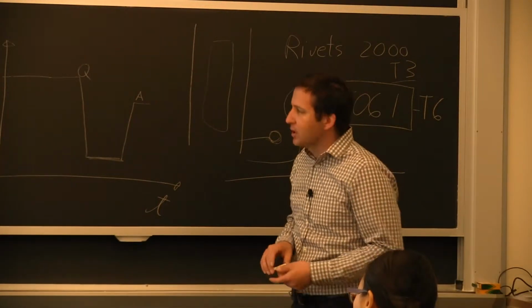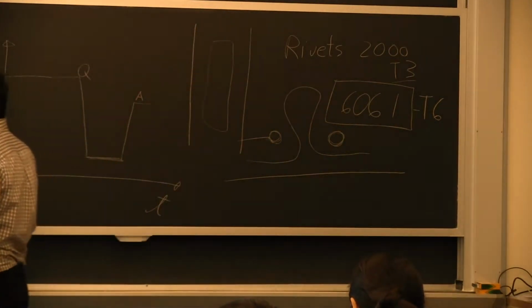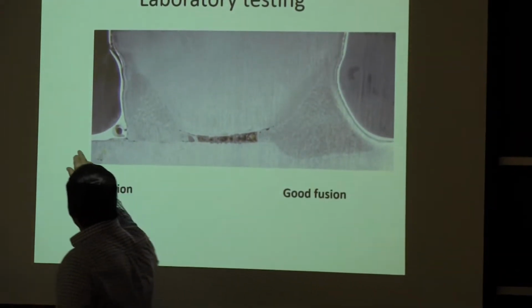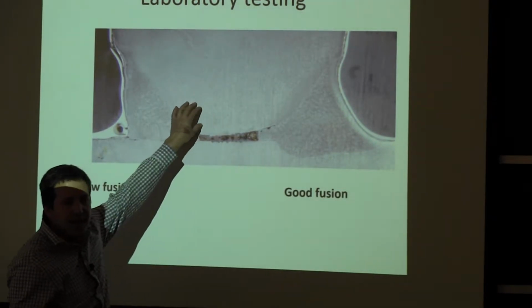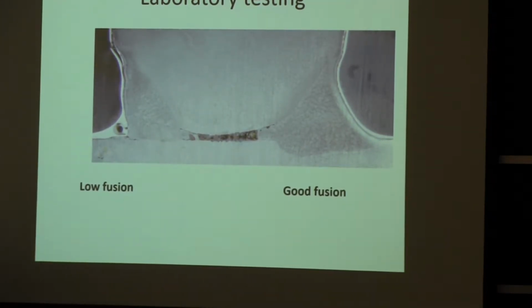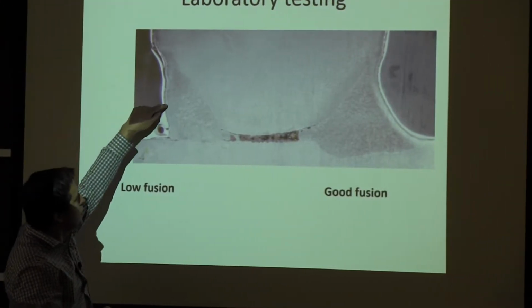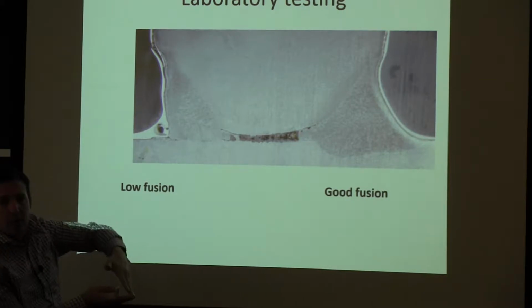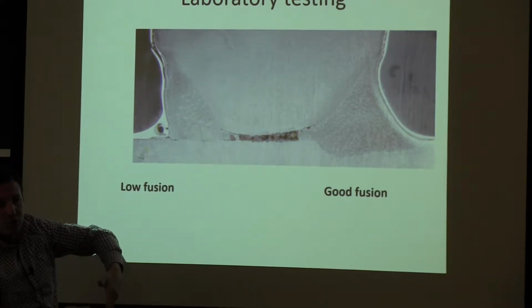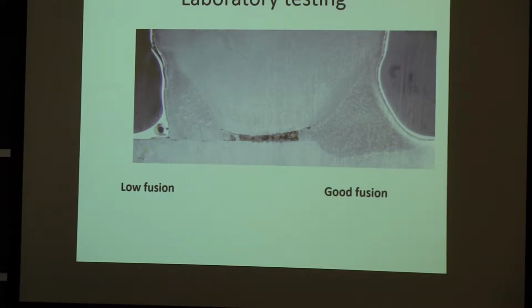If you remember, we talked about these roof joists. The roof joists were a thin piece. Here this was a tube, so a thin-wall tube for the chord, and we had these bars as diagonals that were a lot thicker. And what I was pointing out, it's not a weld that's easy to do because you have to enter a corner as opposed to being at right angle, just doing a fillet weld. We call it a flare bevel. That's the name of the detail.